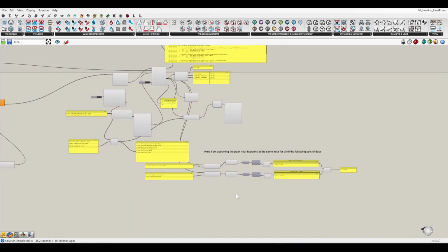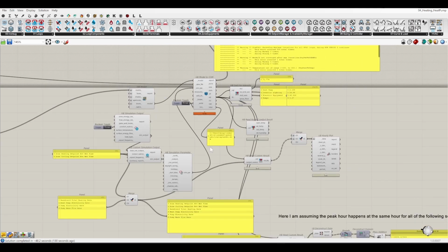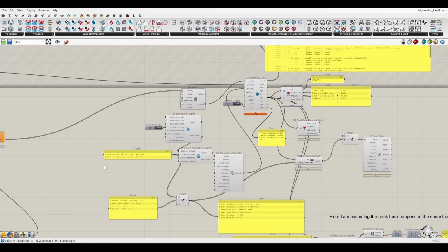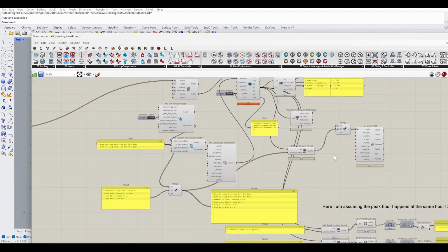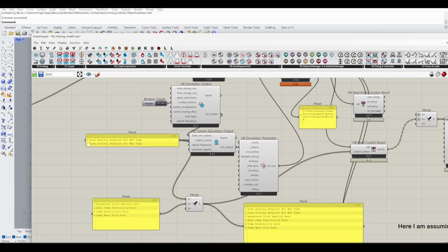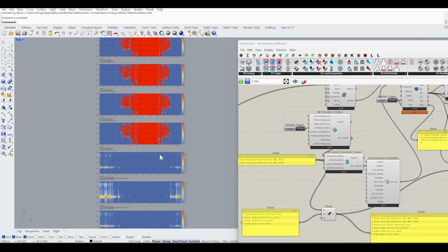Now let's look at, before checking the system and making conclusions, we have to check if any of the zones has unmet hours. Since we have already requested the unmet hours for each zone, we can visualize them.